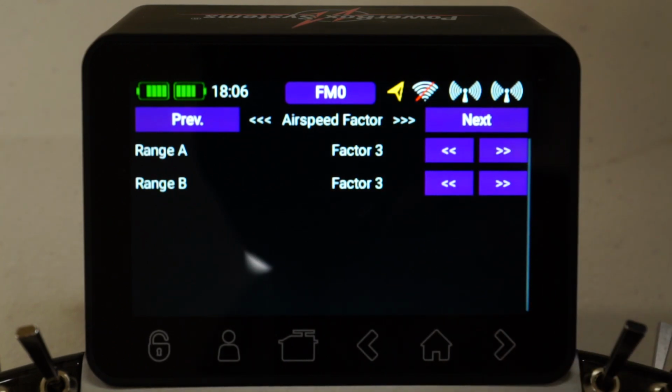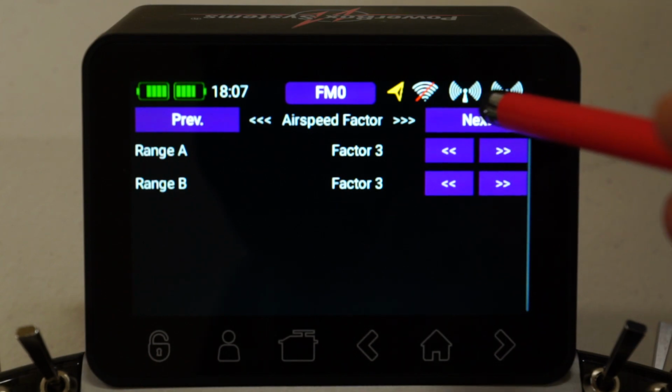So basically in a high speed situation, you don't necessarily want the same gain, otherwise you can get oscillation of the flight surfaces. So, you fly a couple of 100 kilometers an hour in your jet, the gyro might reduce down to a particular gain setting. However, when you come in for a landing, as you slow down, the gain will increase back to the default setting you set.